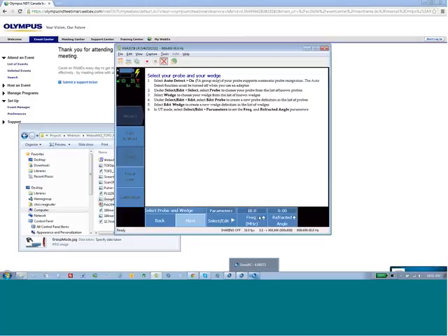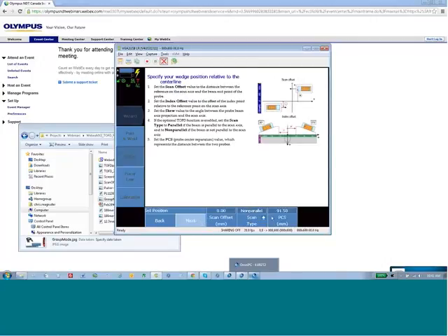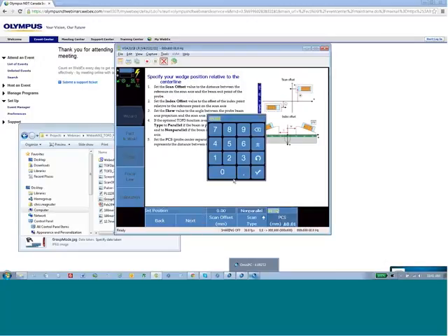We will enter the angle of the probe just for recording purposes. It's not relevant to the calibration. Setting the frequency of the probe will automatically set the correct pulse width. We can enter any scan offsets and the calculated PCS for our group.